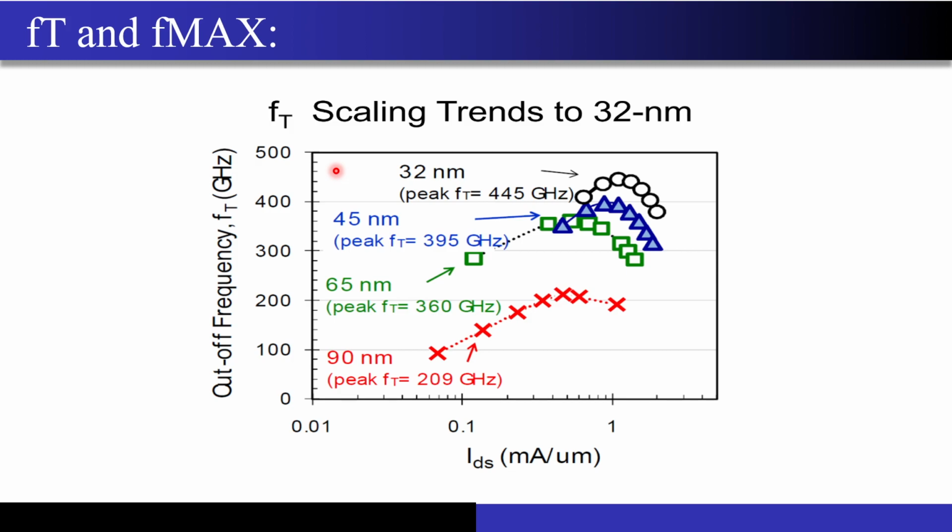And those capacitors will now start to play a very important role in analyzing the circuits at high frequency, correct? So when you apply a certain current into the MOSFET, even though it seems that the gate has an infinite impedance, now those CGS and CGD capacitances will lower down that impedance, and you can actually formulate a figure of merit called the current gain, where FT, that is the unity current gain frequency, is where the current gain of that MOSFET will drop to a value of 1, correct?